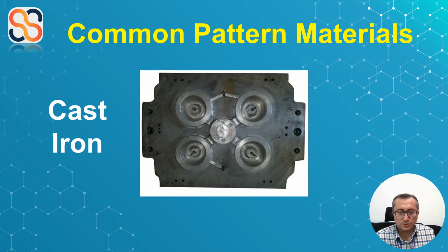When it comes to cast iron, it should be noted that it is a popular option because it is cheaper, stronger, tough, and durable. It produces a smooth surface finish and has good resistance to sand abrasion. However, cast iron patterns can be hard, heavy, and brittle, making them prone to rust in moist conditions.